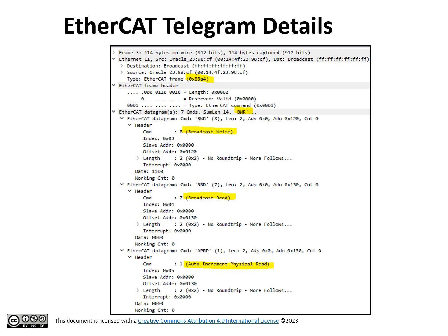ICS communication messages are transmitted and encapsulated on EtherCAT as a UDP payload using port 0x88A4, 34990. EtherCAT is highly susceptible to denial of service, DOS, and spoofing attacks due to lack of authentication. A snapshot of the details of a captured EtherCAT packet are shown in the figure below.